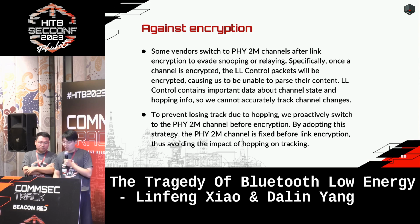Some vendors switched to PHY 2M channels after link encryption to evade snooping or relaying. Specifically, once a channel is encrypted, the link layer data package will be encrypted, causing us to be unable to parse its content. And the link layer control contains important data about channel state and hopping info, so we can't actually track channel changes.